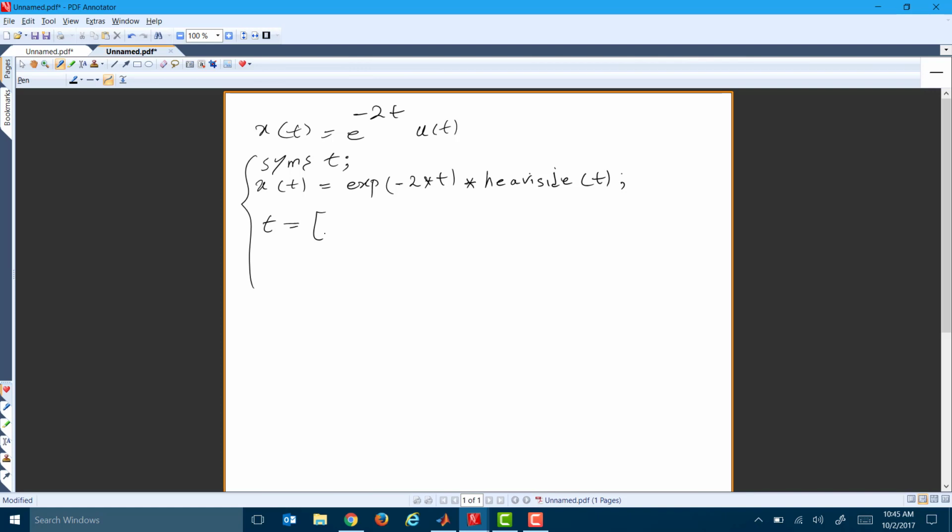So let's say now it's the time that I want to plot this function in MATLAB. Then I go and I define the variable t. Let's say I want to plot this function from the range of minus 10 to 10. So t is defined at this moment before writing the function. Now let's say I want to plot it. So I'm going to use the function fplot in MATLAB after 2016, so the new version in 2017. Fplot is used as opposed to ezplot, which had some problems in the discontinuity points. So fplot x and t.